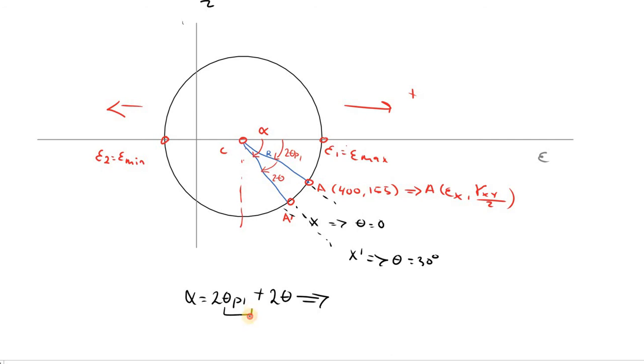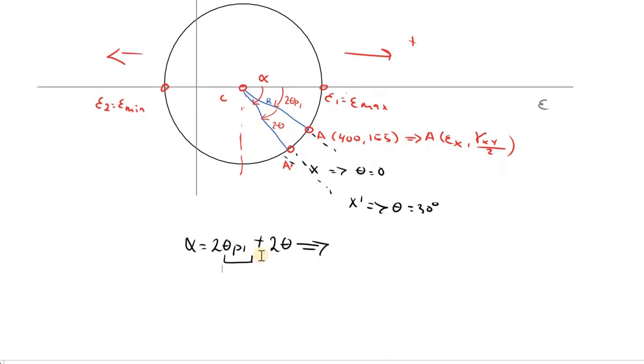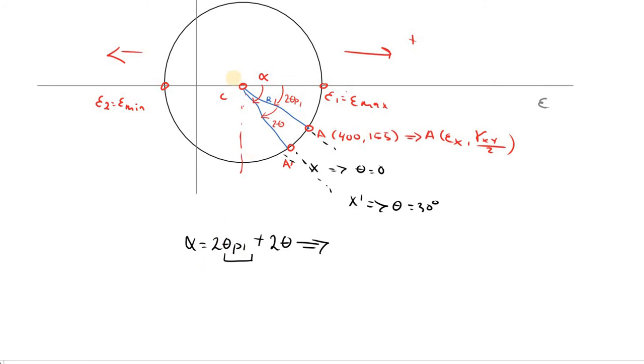I don't know this theta P1, so before we can figure that out, if we just go ahead and look at the graphical intersection between our reference point and Mohr circle, what we'll find from our reference point all the way up to the normal strain axis, we will have this dimension in there as our shear strain divided by 2, which we have written down here.